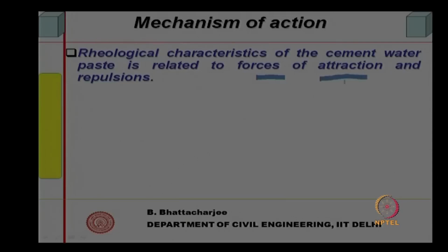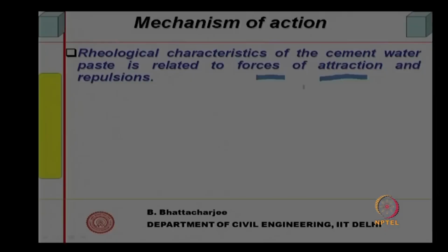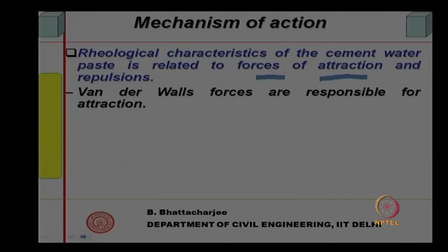In the beginning when you add water, the viscosity of the paste that you form, or how much force is required to cause it to move, deform or yield, are all functions of the forces of attraction and repulsion between the cement particles themselves. Two types of forces we recognize. One is the van der Waals forces, which are responsible for attraction.